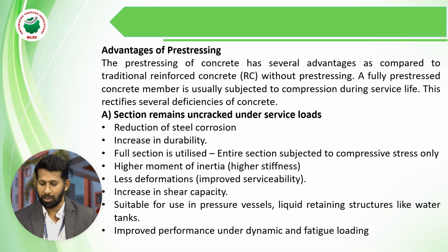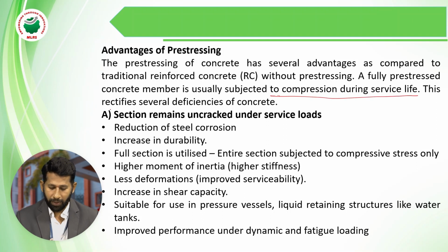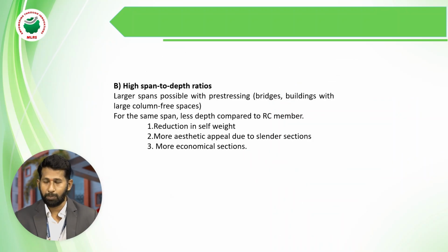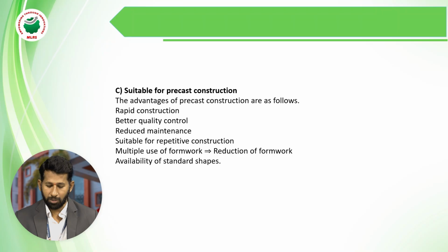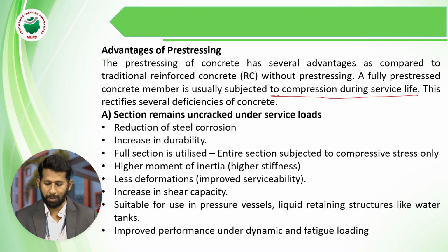Prestressed concrete has several advantages compared with RC structures without prestressing. A fully prestressed concrete member is usually subjected to compression during its service life. This rectifies several deficiencies of concrete. First, go to the advantages. First, the section remains uncracked under service load. Second advantage, high span-depth ratios. Third one, suitable for precast construction. So now go through the first one: the section remains uncracked under service loads.